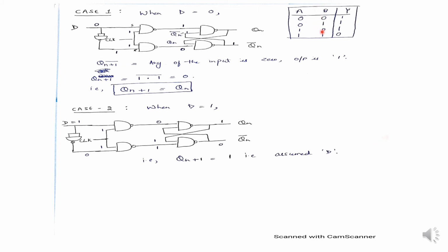That NAND gate truth table is given to you here. So if D equals 0, that means this 0 is going here. Okay, and this is the NOT gate. So if this is 0, that means 1 will be here. So we will solve this gate first because this input is 0 here. If 0 is given to the NAND gate, what will be the output? The output will be 1 here.